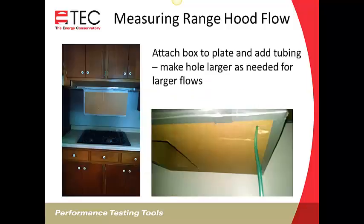Then we taped that box up in place and added a tube in the corner. Now we're ready to take that measurement. I'd recommend bringing something to prop that box up, because especially if you're using heavier materials, tape isn't going to stick. Sometimes you're going to be trying to tape to greasy surfaces that won't work so well. So you're going to want to bring some things along that you can use to prop that box up, to hold the weight up so it doesn't come down in the middle of your measurement.